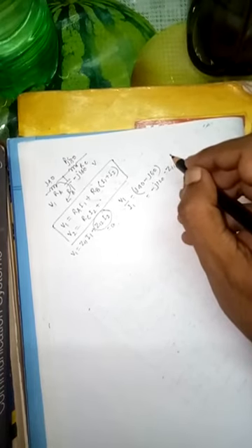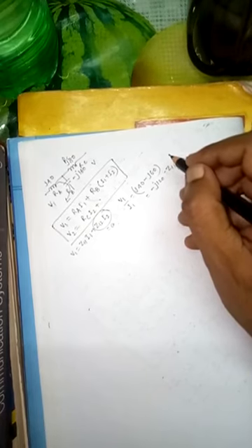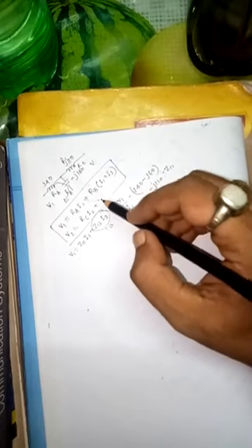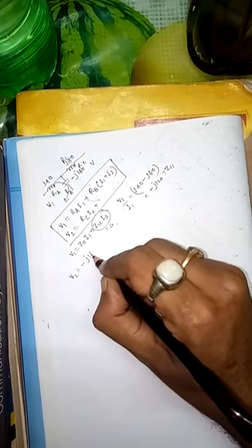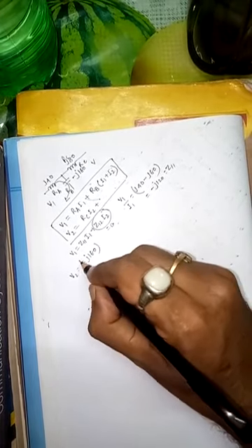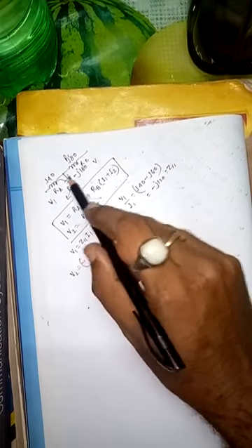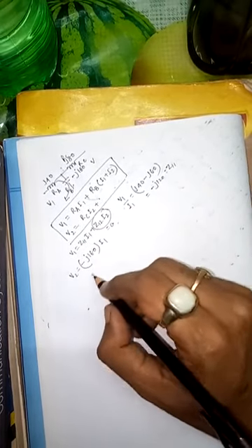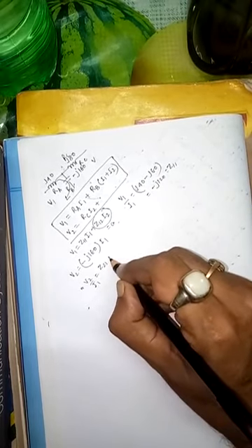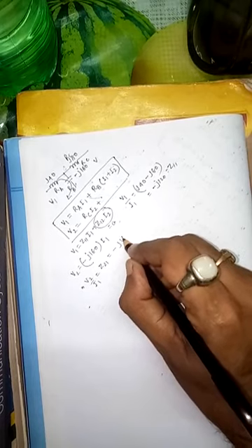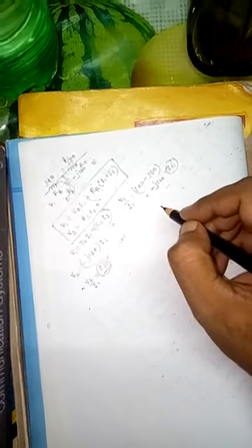So what is Z21? Z21 means, if we are having this particular V2, what is the value of V2? V2 equals minus J160 multiplied with I1, because it is open circuit, no current is passing through this, so just this particular value is V2. So finally V2 by I1 is Z21, that is minus J160, and this is Z11. In this way you have to find it out.